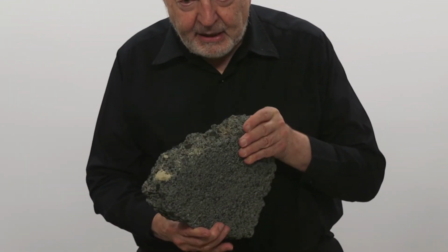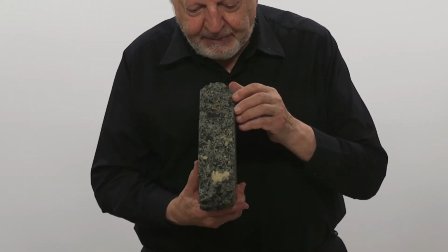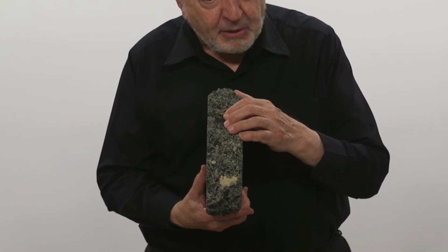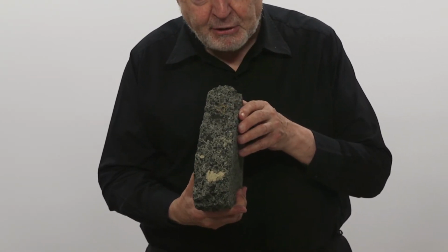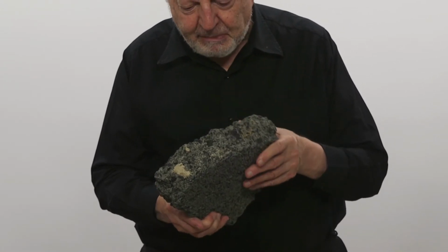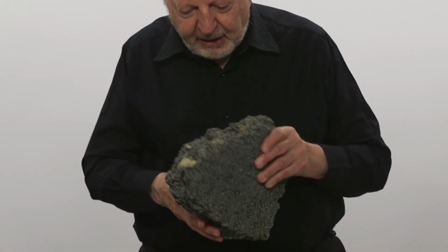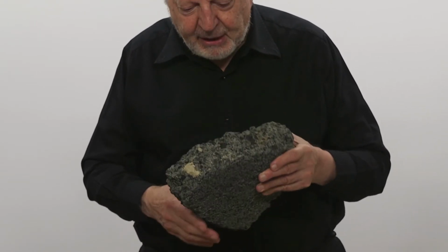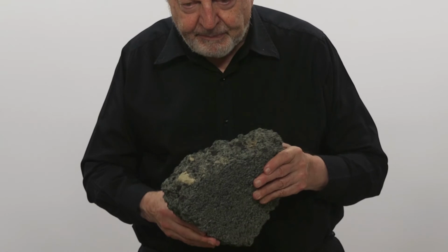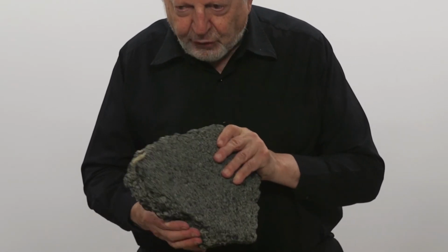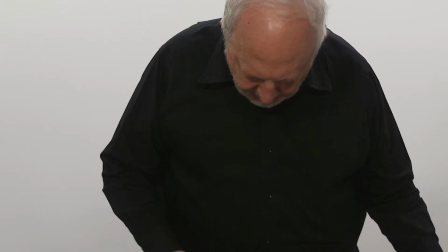Many buildings were made of solid concrete. So in the 19th century, when you speak about a concrete building, you're not assuming reinforced concrete as you would today. It can be just solid lime concrete. But here's a variation. This material here contains coke breeze. So it's a concrete, but instead of having stone like basalt chips in it, this is coke breeze, which is a byproduct of gas making. So from the 1850s onwards, these lightweight coke elements were available for almost nothing, and they made a very good insulating lightweight concrete. And not only was it used for structural walls, but also for bricks.